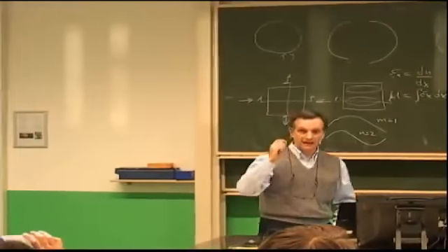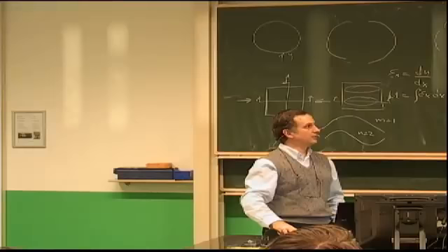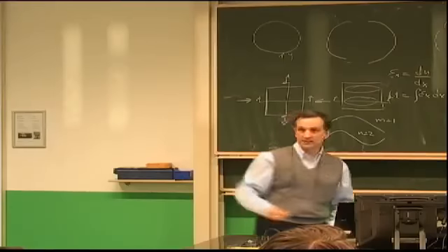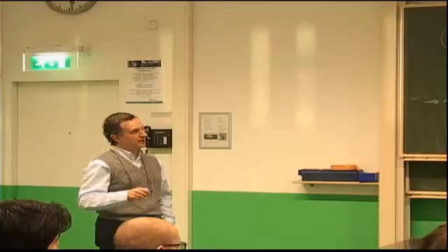For composite, you will get this curve for this layup. If you change the layup, it will change the curve. But for purposes of comparison, aluminum appears to have significantly higher buckling load. But you have to account for the densities, obviously. So if I have the same thickness, aluminum is 10 to 20%, depending on the aspect ratio, better in terms of buckling load. If I now said I want to make my composite to match this, and let's say I want to match the worst case, the 20%.